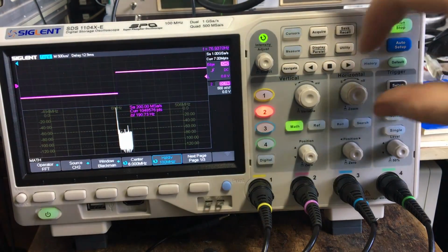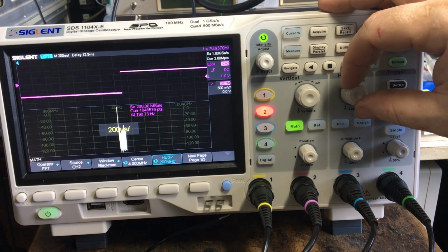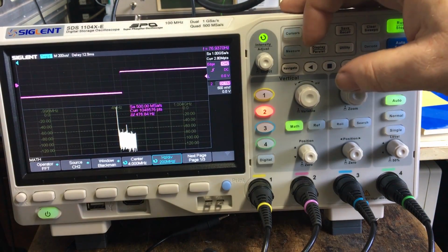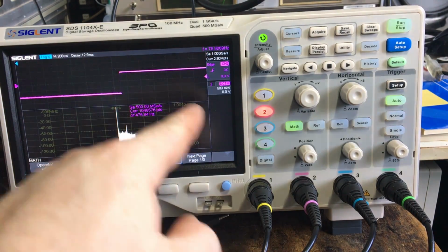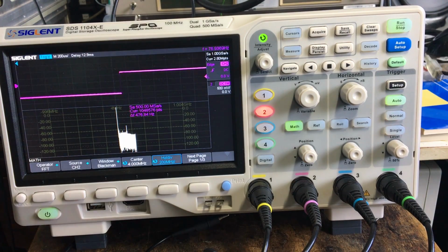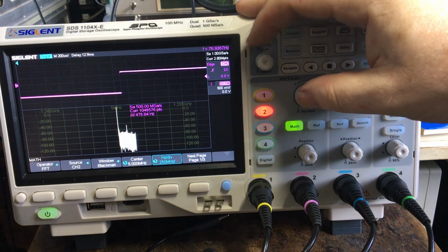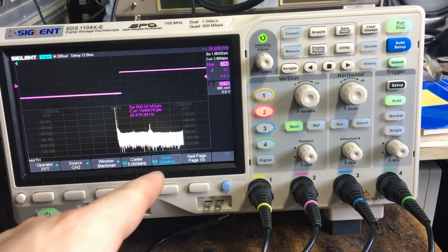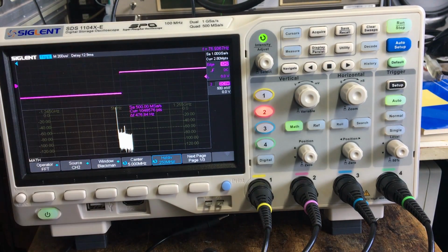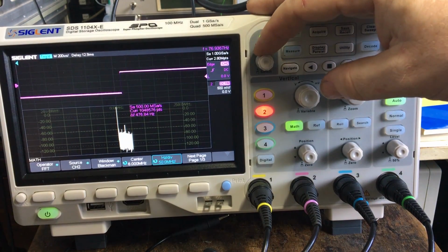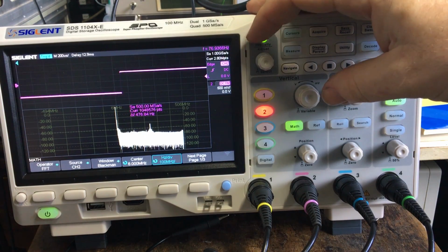So this shows like 500 megahertz in that time base. 1 gigahertz, right? But as you can see, it's nowhere near that coverage on there. So just because it displays it on screen doesn't mean you should actually expect it to do that. It's obviously like a universal software you can have, and it's firmware, and it just does it regardless. But yeah, 250 megahertz per division, 1.2 gigahertz. No, you know, don't expect to do that. That's just unrealistic.